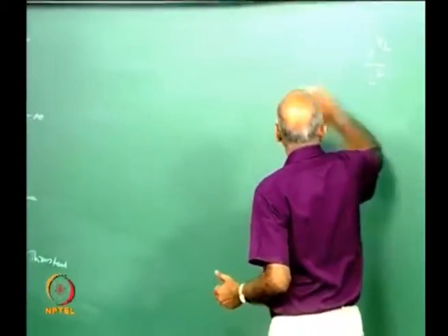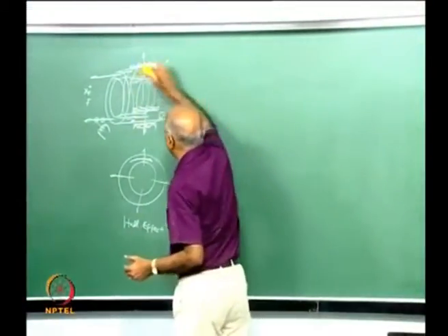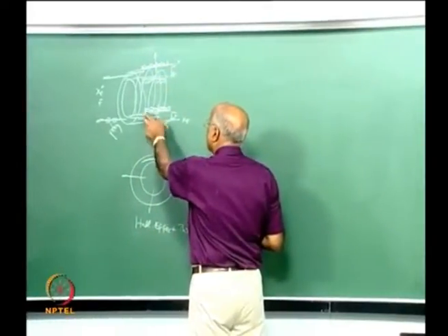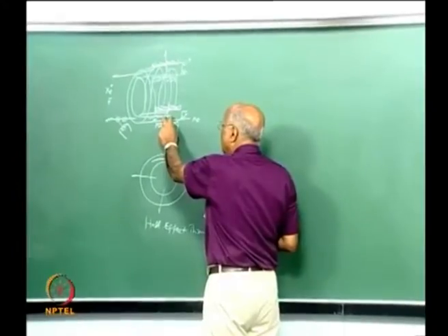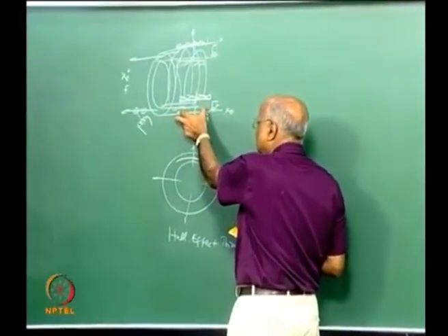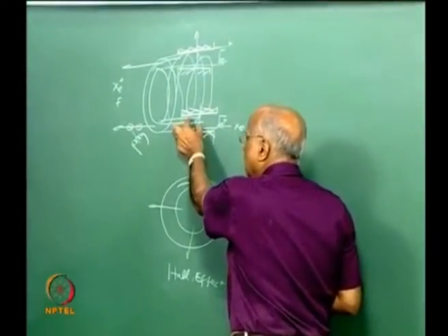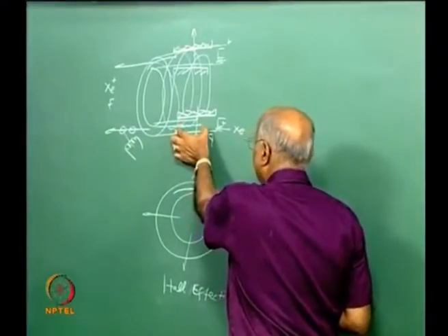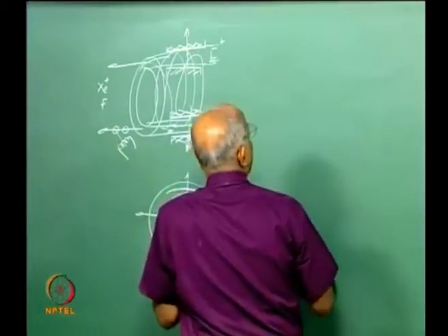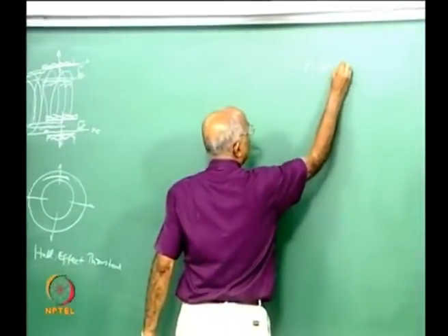Therefore, all we will say is Hall effect thrusters make use of the spiraling effect of the electrons which collide, and since the spiraling effect is used, you do not have things like Child's law limiting the beam current. This is essentially a plasma consisting of a lot of neutral gases. You do not have the problem of sputtering here, and it is an easy thing to use, and I use a low voltage of around 300 volts.